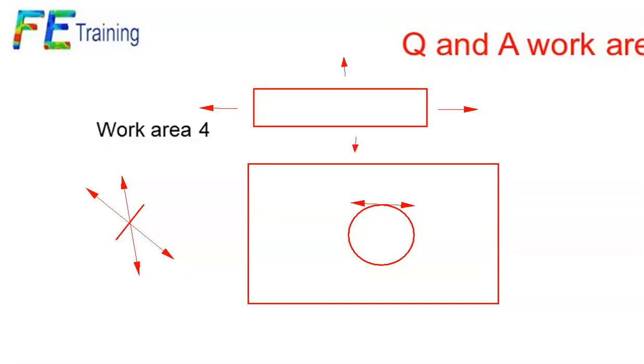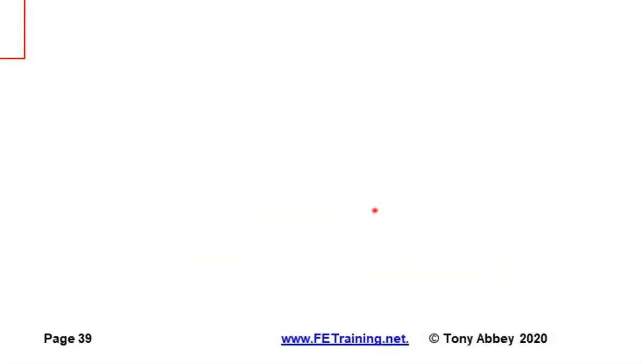Multi-axial, this does whatever it wants to do, this does whatever it wants to do, and we've got a continuously varying stress state in here. So those are the three levels: uniaxial, proportional, and multi-axial. So assuming your question's about uniaxial, then I'd always use maximum principal and swing it around a little bit so it's aligned with the correct direction. I think maybe two more, David. Will that suit us? Okay, good.